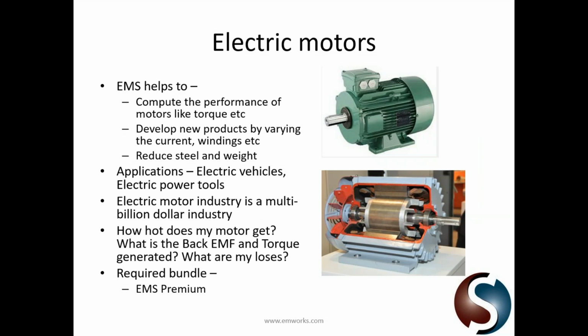Electrical machines is a big application area for EMS. Here, with electric motors, EMS can help you compute the performance of your motors, like the torque speed curve, the efficiency map, etc. One can use EMS to reduce the steel used in the stators and the rotor of motors. This has various applications. Electric motors is a big industry by itself, from electric vehicles to electric power tools. So EMS plays a major role in helping you conceive and design your electrical machines.